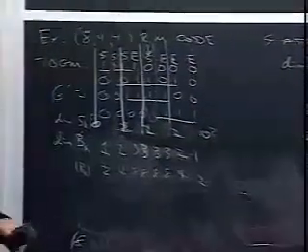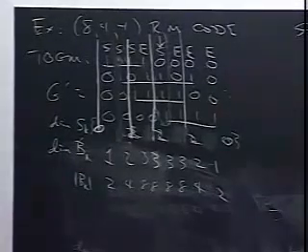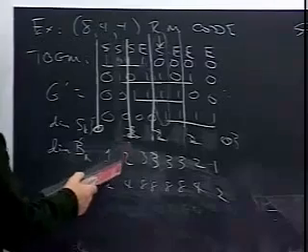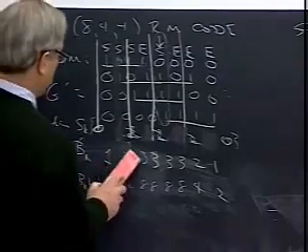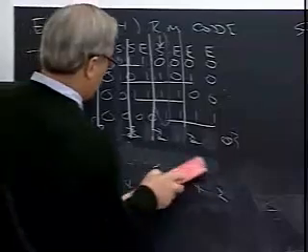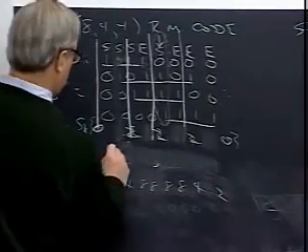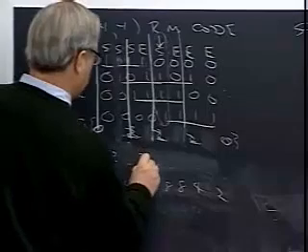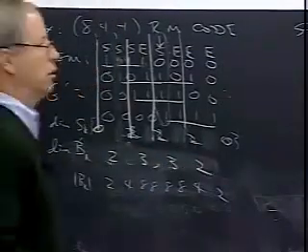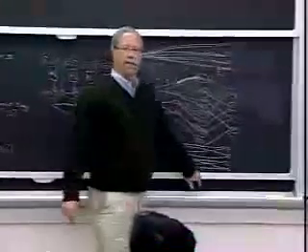They don't change. We just have fewer of them by our choice. What happens to the dimensions of the branch spaces? Again, the theorem is correct. We should just count the number of active generators at each of now these 4 bi-symbol times. So it's 2, 3, 3, 2. Is that right? That is the branch complexity of this trellis down here.